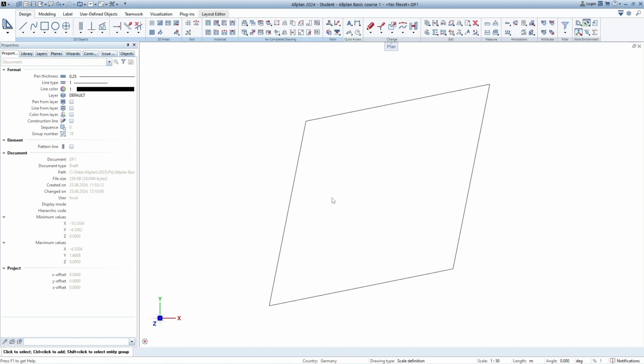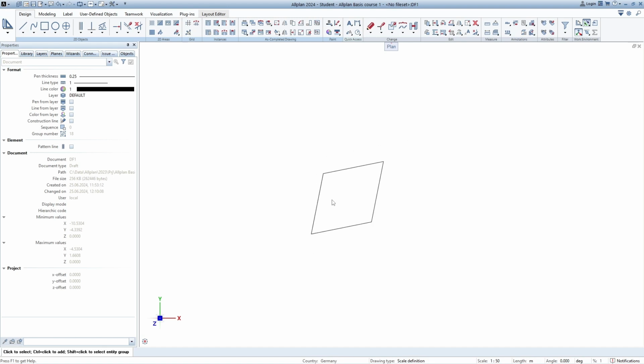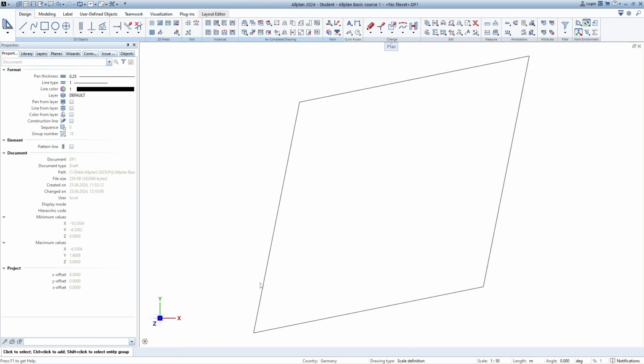And there's also a function. There are 3 options to access this kind of functionality, which is a double click on the mouse wheel itself. So if I, for example, have a drawing and the view is just like that, and I want to use this kind of function, which is called zoom all, I could do a double click on my mouse wheel and basically have a zoom window that is focused on all elements that are in my current drawing.